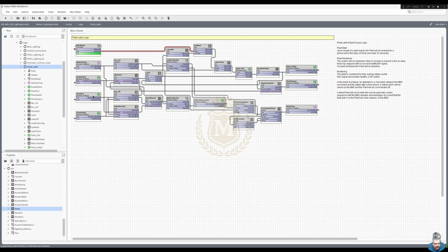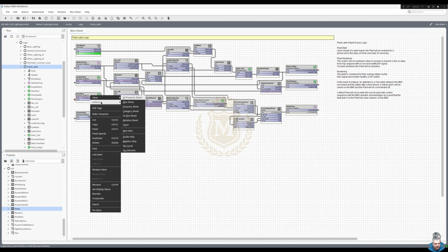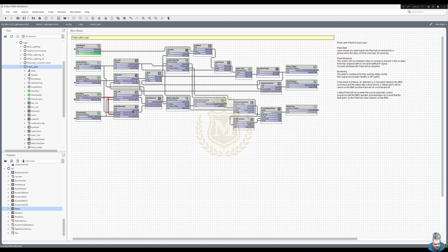We go to enable the run, and we won't get a fault at all, and that timer's not timing. We lose the run, fan belt broken, whatever you want to call it, we've lost the run. We're now timing, and we're timing 30 seconds to a fault.